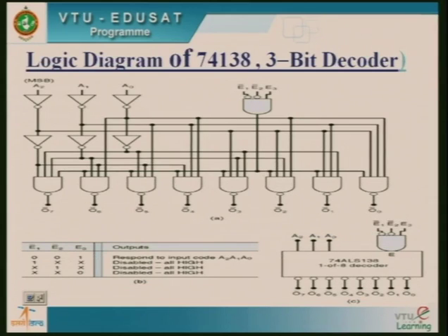So you can just see 74138 is once again a 3 to 8 decoder. You can just see here MSB connected to all 7 lines. So this is a circuit IC of decoder 74LS138. This decoder has got 3 inputs, 8 output lines, and additional pins called enable. So this enable has been given input with 3 signals.